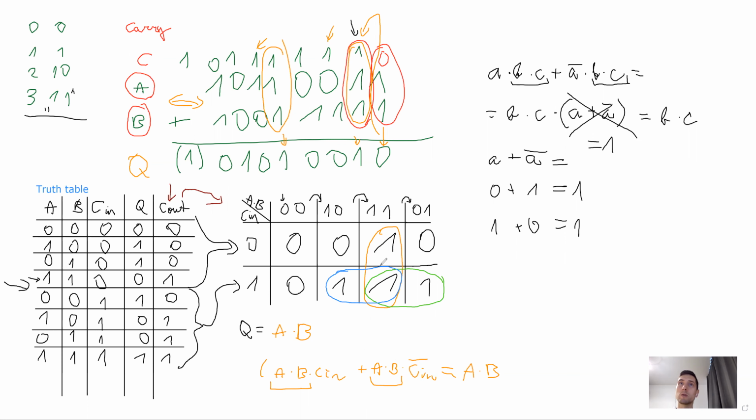So this thing just allows us to graphically identify these locations where one of the terms is inverted and not inverted at the same time and cancel it out. In this simple case, we could have just seen it and done it on paper, but this Karnaugh map allows us to visually detect such places. And in more complicated truth tables with many more elements, we could much easier spot such things.